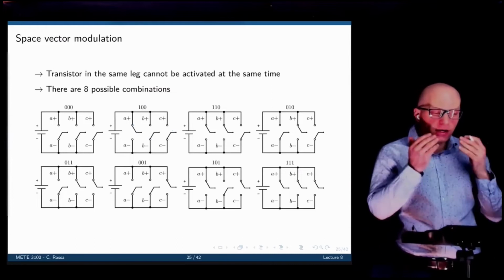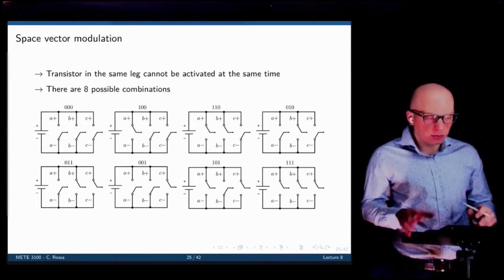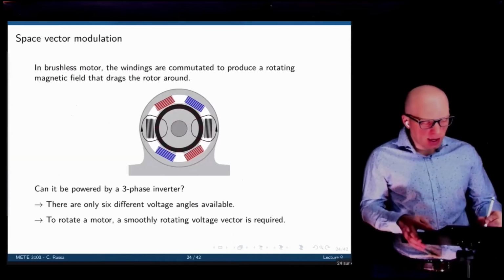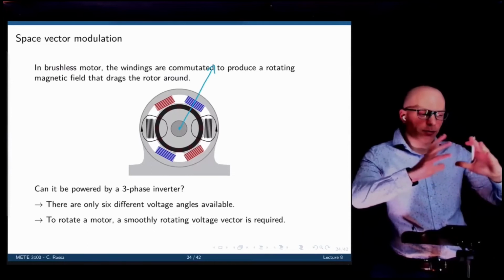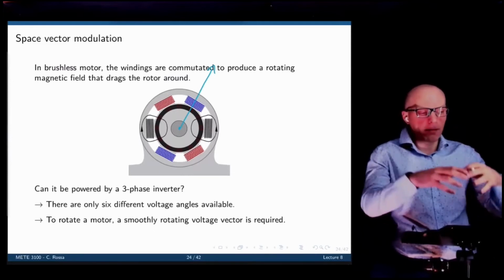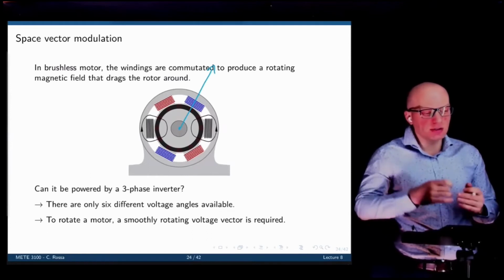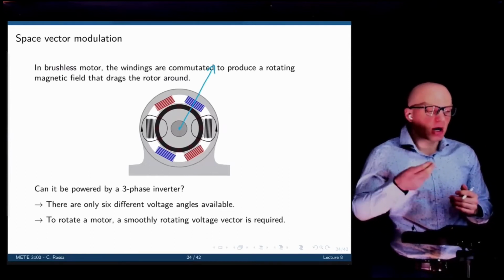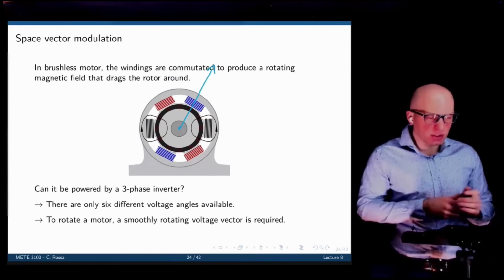When we apply phase 1, when you apply 100 to the inverter, that will represent the resulting magnetic field from the combination of all these 3 coils that are mechanically, physically spaced 120 degrees out of phase, in the same way that the phases are shifted by 120 degrees electrically. So that's the resulting magnetic field.